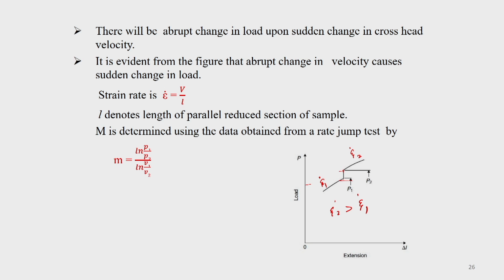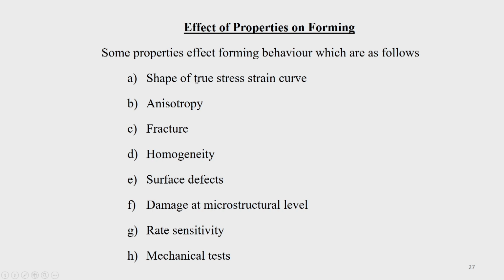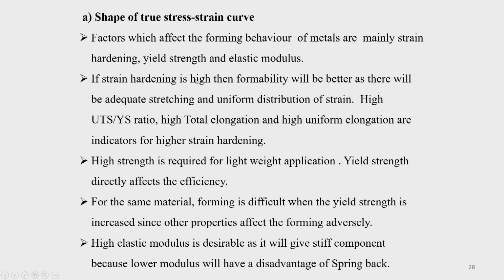That load you take and substitute in this equation, the derivation we have mentioned earlier also. m is equal to log P1 by P2, where P is the load, divided by log V1 by V2, that is the velocity. This will give you the strain rate sensitivity index. Okay, so, I think with this I will stop today.